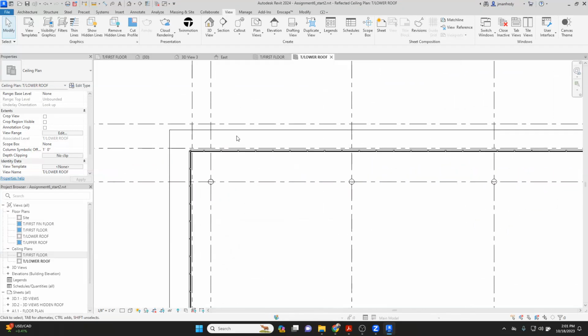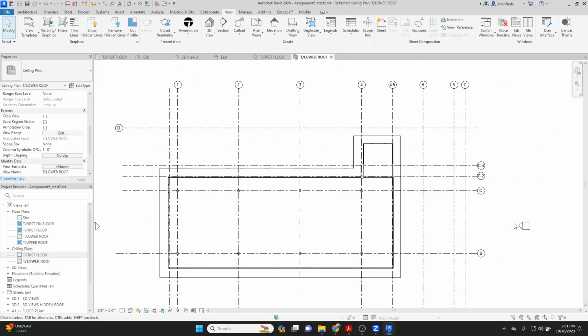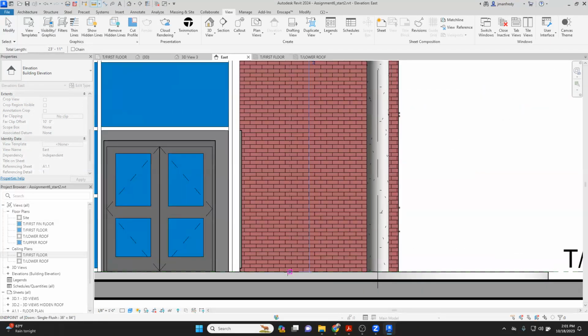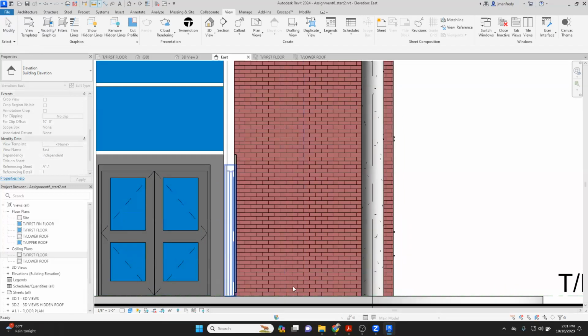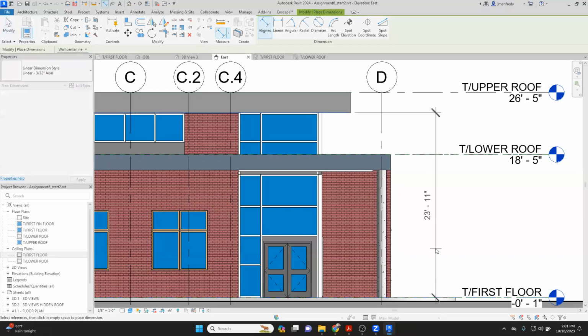Let's make a ceiling up here, and then I'll figure out the height of the ceiling. Let's do it now quickly. This ceiling needs to be somewhere from here down to the floor, which I can barely tell what that is there. 23 feet. Let's start with 23 feet, for example. We'll fix it in a second. Anywhere below this point right here. Now this is about 23 foot 11. So the top of the ceiling needs to be below 23 foot 11, or the top needs to be aligned with 23 foot 11.